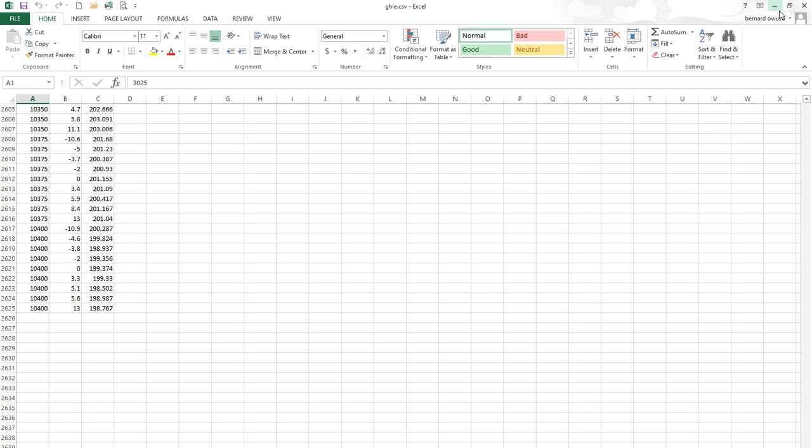You have marked your changes. What you are interested in is the profile, not whether it curves or not. So you have picked the stations and you have picked the levels. For this particular case, once the invert level is just one line. But we are looking at a situation where you also have maybe the left edge and the right edge. So we have offset to the left, offset to the right, and at the center.